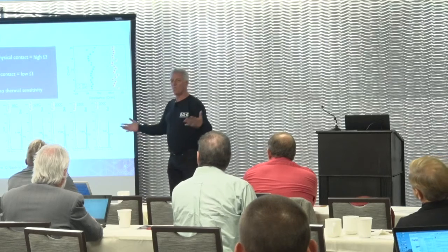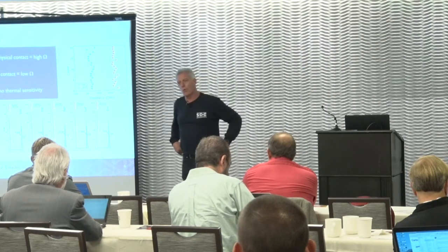states. Some of the other random data I threw together on this slide covers things like, what's the performance of this? Well, it's only a few angstroms of movement. The fundamental cell performance is 5 nanoseconds. And it's a balanced read and write at 5 nanoseconds. So it's a persistent memory cell that runs at 5 nanoseconds. What could you build with that?